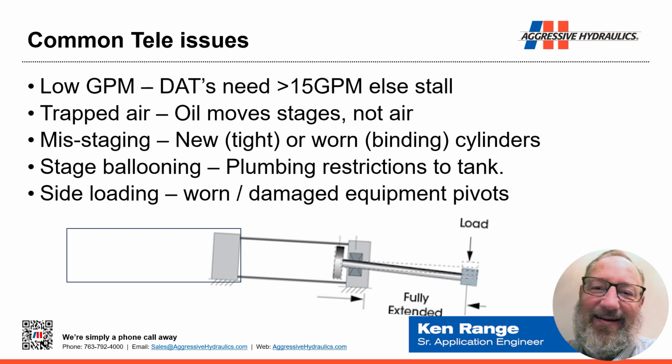The large side of the piston, which is a larger area, if that oil isn't allowed to leave, that large area of the piston is building pressure against that oil that might be low pressure, but it still has pressure. The force that's created by the blind end of that piston can be so great that it can cause the case of the cylinder to expand or balloon.